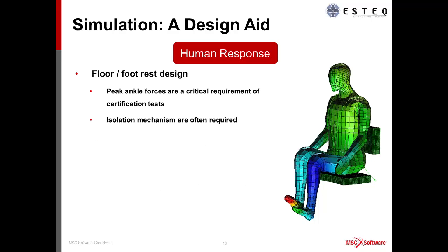And the final point that I'll make under human response is with regard to floor and footrest design. The peak ankle forces are a critical requirement of certification tests. This is one of the more difficult criteria that vehicle designers find to meet.